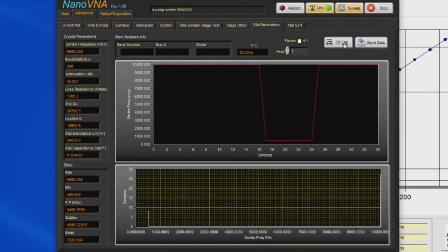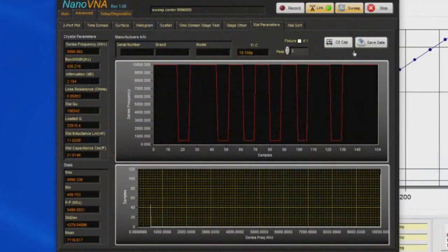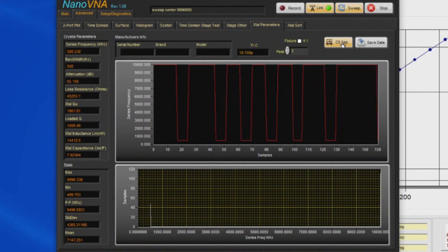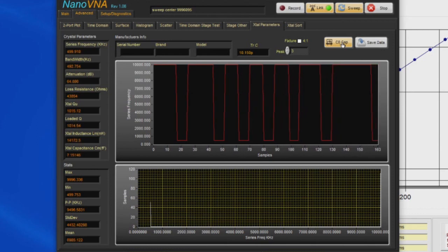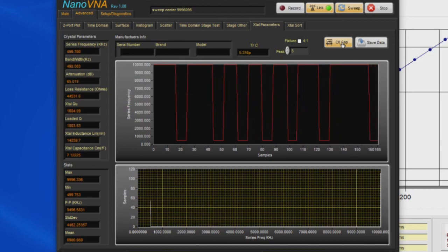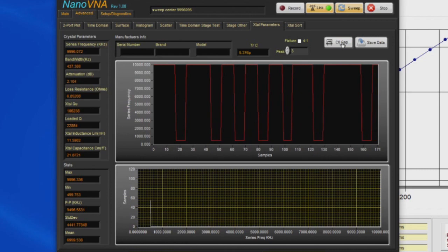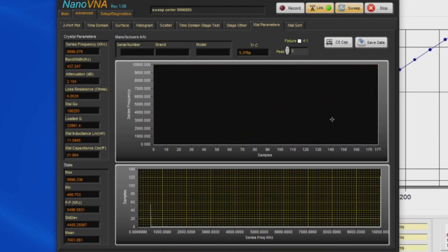That's just by chance. It's not normally going to read that tight. So now let's insert our crystal again. Again, we'll select C0 cap. And you can see this particular part measures roughly 3.7 or so, 3.8 picofarads. And again, let's just go ahead and clear the chart.